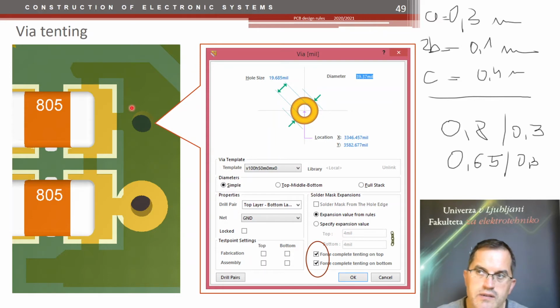So you should cover it. So now you have a pad that is isolated with the top solder mask, and it is connected to the copper plane with thermal reliefs. And this would assure you that your soldering would go smoothly through.